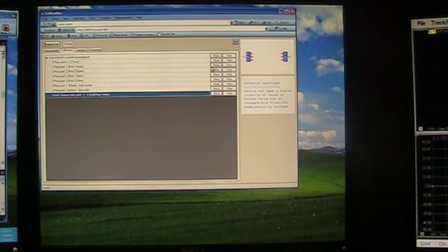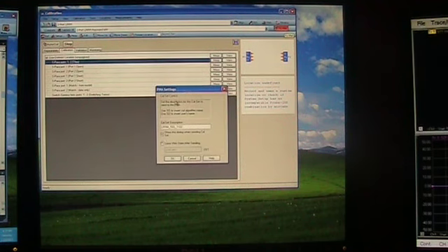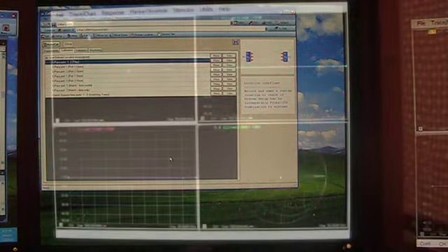Okay, the last step in the calibration is to step on the through path, and in this particular case we measure switching terms internal to the network analyzer as well as the actual S12 through path. Once this is completed with WinCal, we'll ask it to compute the error set, and then we'll send it down to the network analyzer and we'll give it a name that we remember, in this case LRRM50G1102. And now that's been stored in the network analyzer. We'll move back to the network analyzer for a few of the next steps.